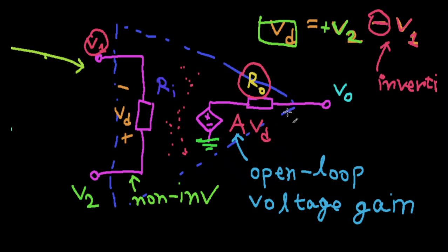At the very least, the way we drew this circuit, obviously, if you just think about it, or even apply KCL, there's no other wires or connections here, right? So the current here is zero. So there's no potential difference across R sub 0. So what you'll get is your V sub 0 here is actually equal to the potential difference of this VCVS, your voltage dependent voltage source.